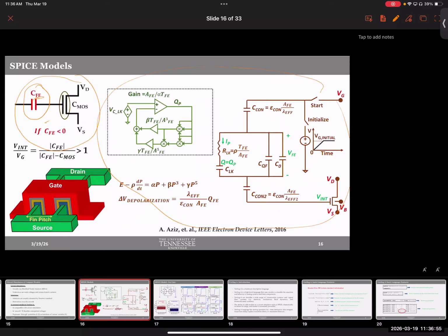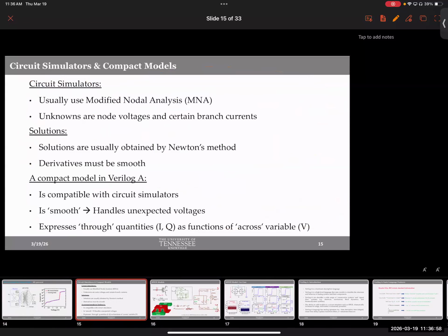for the simple reason of, I hope you remember, there is a principle of compact modeling. If something dramatically switches from one level to the other, there is a sharp increase in the derivative. Remember, make sure the derivatives are smooth. So when you do, if something happens, do this, else do something else, there is a sharp transition at a given threshold. At that threshold, what is the derivative? If it is I versus V, the derivative of dI over dV will be infinity, which is going to lead to convergence issues.